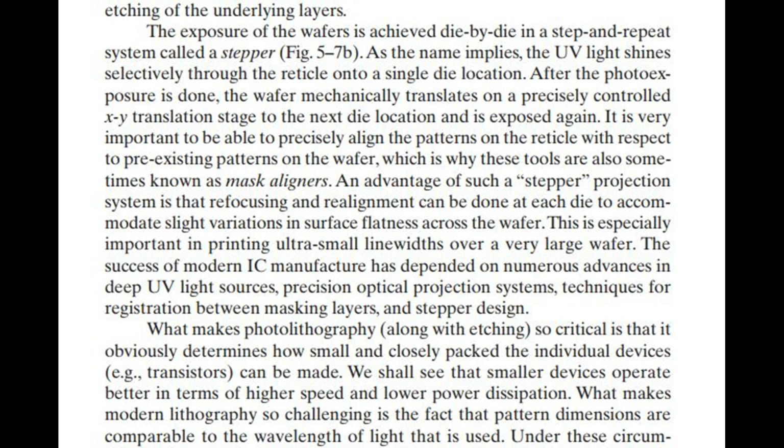It is very important to be able to precisely align the patterns on the reticle with respect to pre-existing patterns on the wafer, which is why these tools are also sometimes known as mask aligners. An advantage of such a stepper projection system is that refocusing and realignment can be done at each die to accommodate slight variations in surface flatness across the wafer. This is especially important in printing ultra-small line widths over a very large wafer.